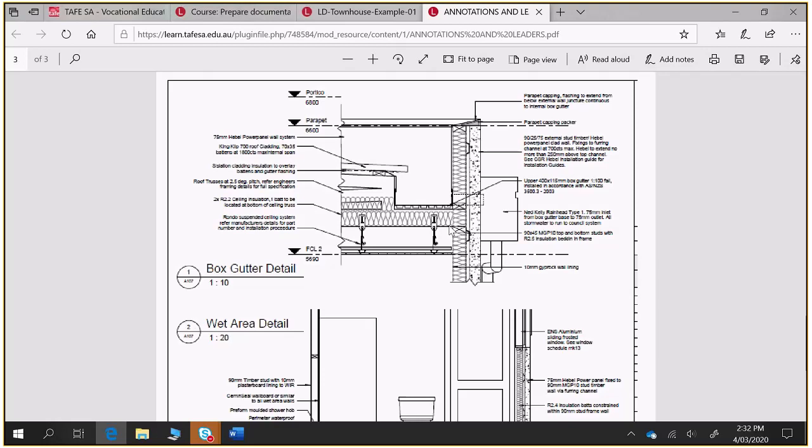There's something that comes with time and a bit of practice. But I think if you want to dress up your drawings and make your drawings really pop, or look really nice, that's a way of doing it, is to think about your line weights and experiment with line weights. But just remember that heavy elements that are cut through, thicker lines around your 0.5, elements that are in the distance, really thin lines like 0.09. And then your other bits, something in between those. 0.25, 0.18 and 0.35 we use a lot.